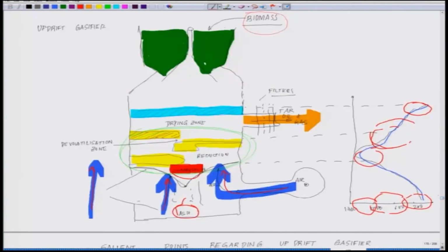So, look at it. Here the ash is getting collected as the air is moving. Here all the combustion and all the chemistry is happening, and the ash which is coming out is now falling down like this through the grate and it is getting accumulated out here, whereas most of the gas or products which you needed, the product gas, is all forming out here in this location.